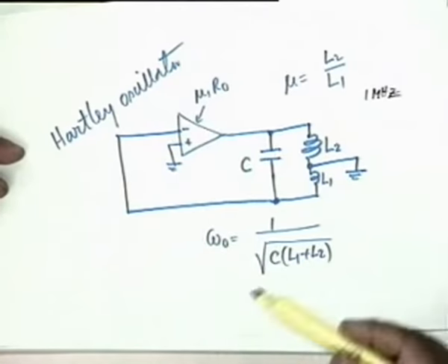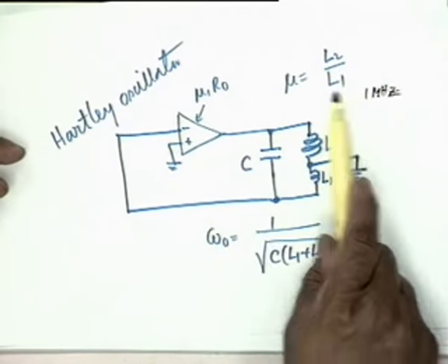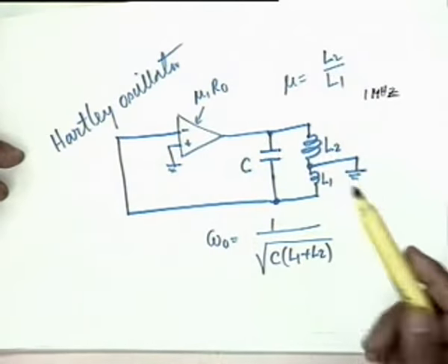If you have 2 inductors, they couple with each other. There is a mutual inductance. Not only that, any other circuit element nearby will also get coupled. And therefore the whole circuit becomes an island of electromagnetic interference. Nevertheless, these are done. One of the inductors or both the inductors have to be shielded, and very simple shields work. Just raise an aluminium partition between the two. You just have to break the magnetic lines, that's all. Okay, simple shields do. Of course, in the market, sophisticated shielded inductors are also available.